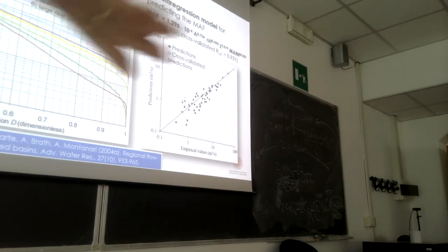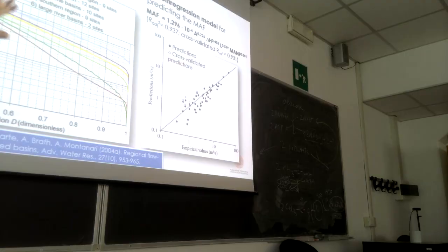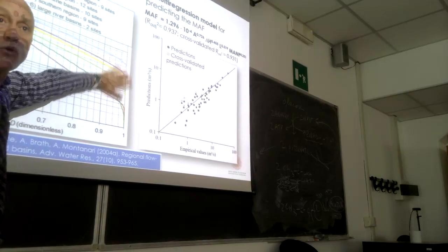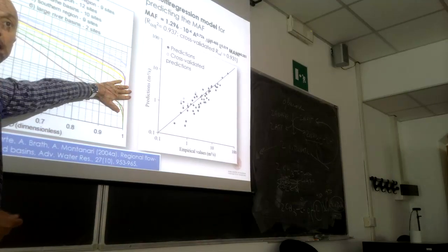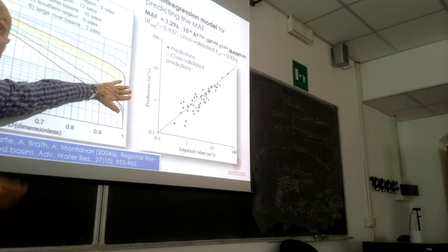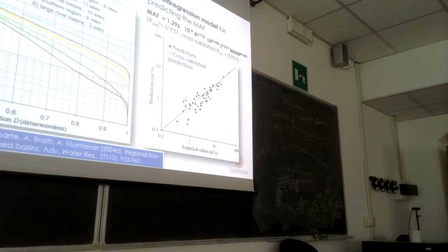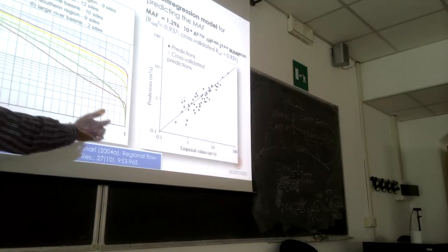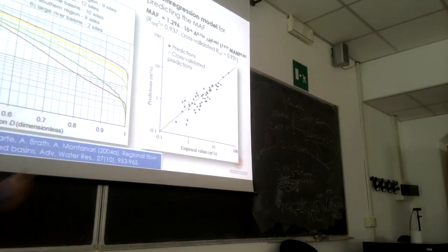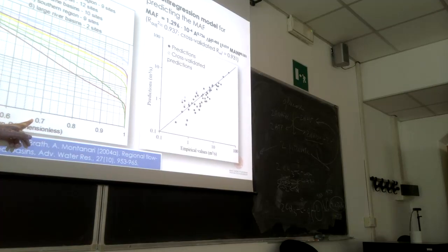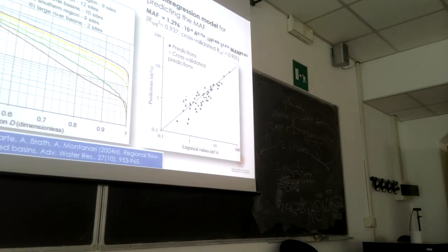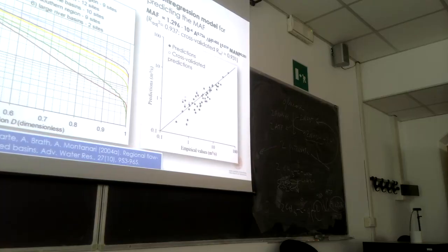And what do we see from this portion? That more or less, wherever the region is, the mean annual flow normally is associated with a duration of 30%. Okay? Because the fact that they all intersect each other here, and here you see 1, it means that this is the duration associated with the mean annual flow. Okay? Sufficiently clear?